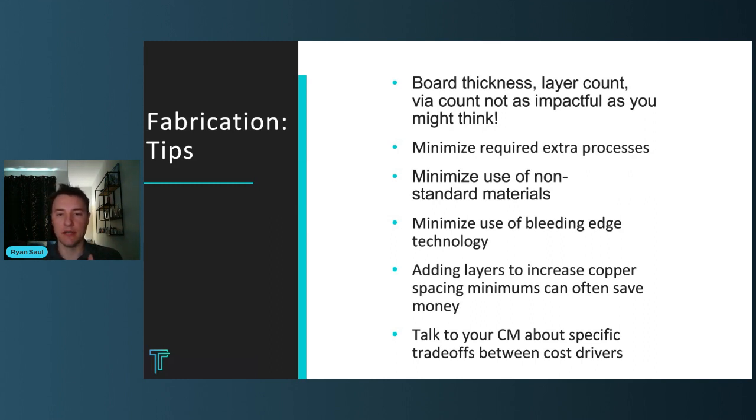They're going to etch, of course. They're going to drill again. They're going to plate again. And you're going to end up adding another week to your fabrication and potentially 2x the cost, if not more. So if you can avoid those buried drill pairs, you should do that.